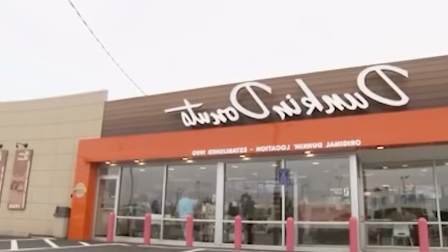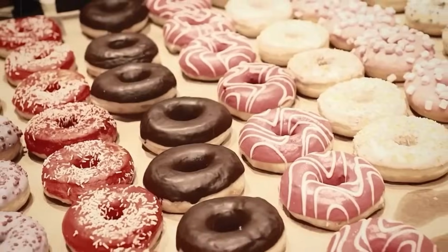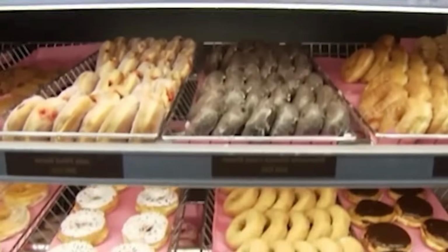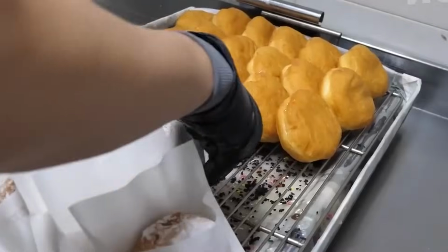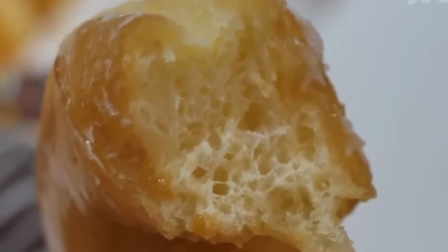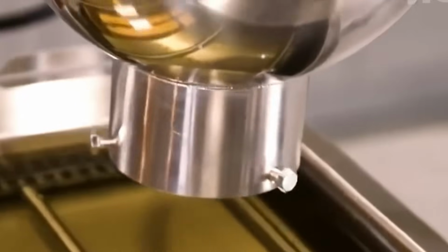Packaging begins with automatic tray erecting. Flat paperboard blanks are fed into a forming unit that applies glue and folds trays into shape. Formed trays move beneath pick-and-place units with vacuum suction cups that deposit donuts into each cavity.